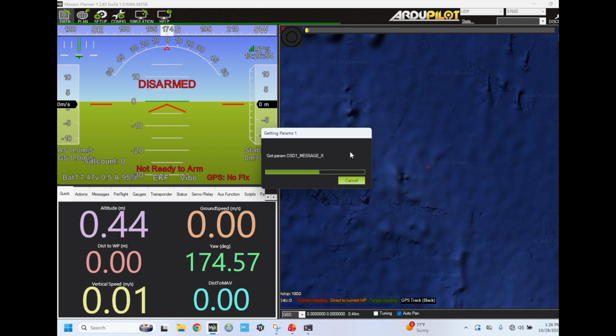But the good news is that it can connect up to 10 kilometers away. So I invite you to try this at the Arc. Try this one. Fly all the way to the other side of the Arc. You should have totally stable Mission Planner signal. No problem. As long as you're patient enough. Now, it also means that if you're flying racing, this is not a really good way to do racing. The latency is significant. And so if you really want responsive stick and rudder control, you wouldn't want to use this protocol. You'd want to use Crossfire if you're a drone racer.